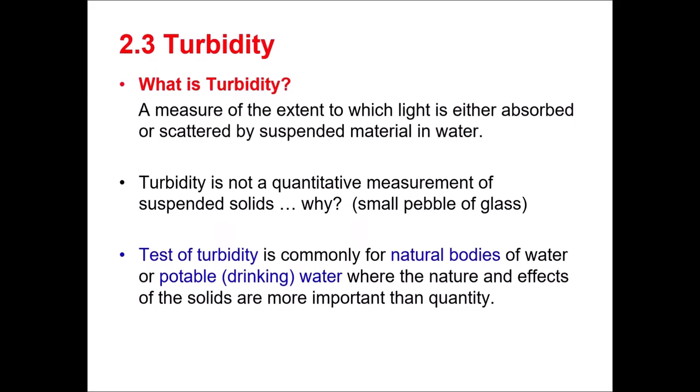And here, turbidity tests are usually done for natural water or drinking water. The reason is that in these cases, it's more important to know what kind of particles are in the water and how they affect it, rather than the exact number of particles. For example, a few very fine or harmful particles can make the water unsafe or affect its clarity, even if the total amount is small. Okay?